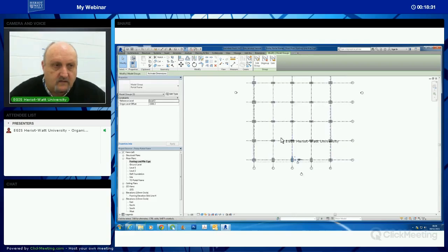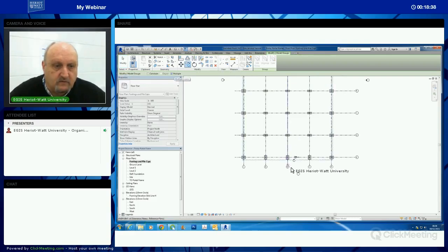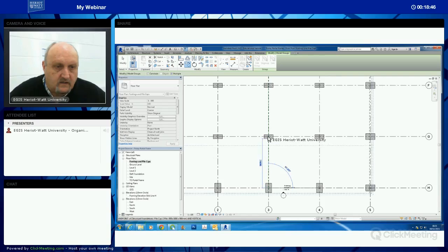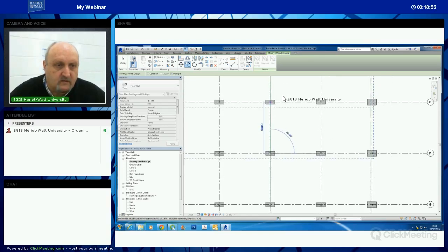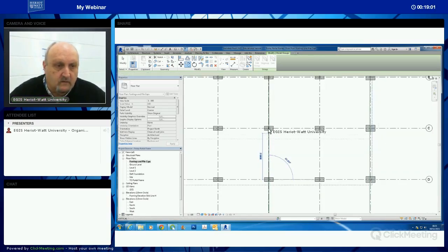It is selected. So again, I have to go to copy, make sure this says multiple, because I'm going to copy it all the way up through the building. I don't want to copy it at once. So in here, group origin, copy, and then carefully place it in the center of the structure, all the way right up through. Carefully don't miss one, otherwise you'll have to go back and redo that particular copy in.